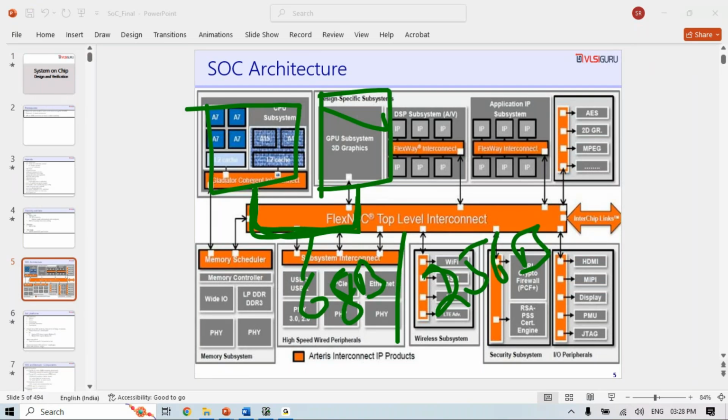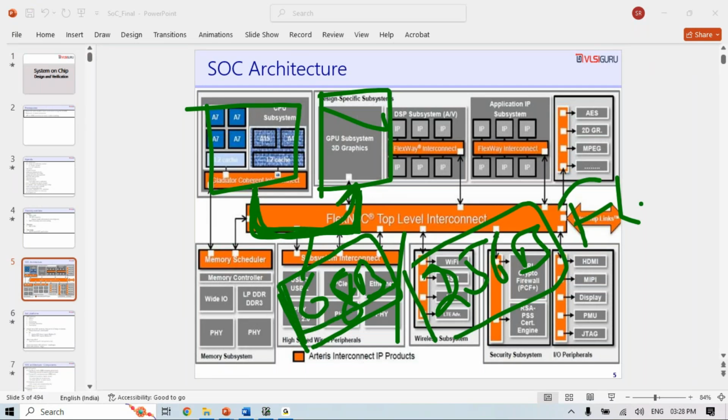When we are talking about CXL, even though it's one separate protocol, CXL is implemented on top of PCI Express. That means you are essentially connecting them through a PCI Express link only. That PCI Express link will carry either 68 byte traffic or 256 byte flit traffic. When the other side receives the traffic, it knows what format the 68 byte traffic will come in.